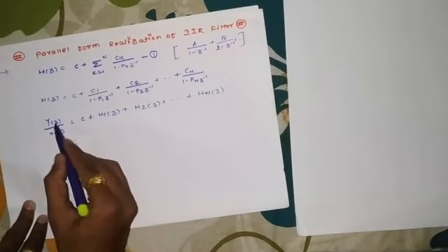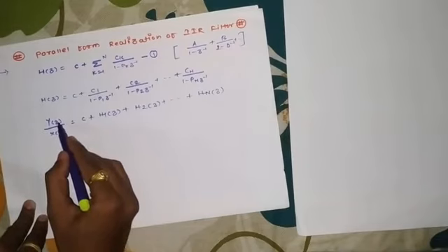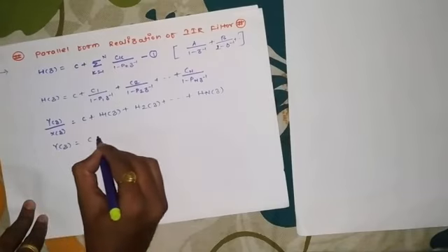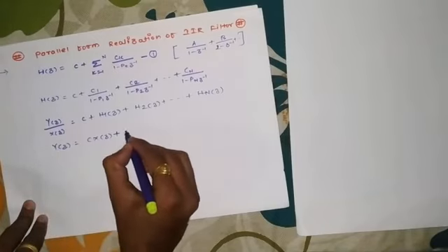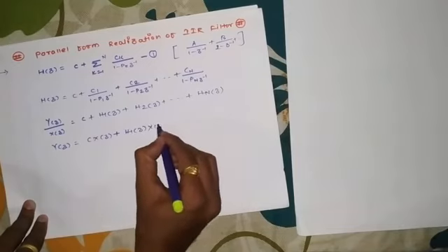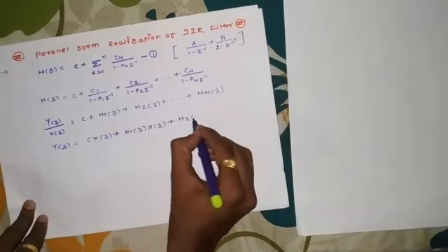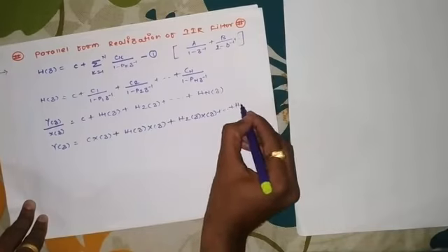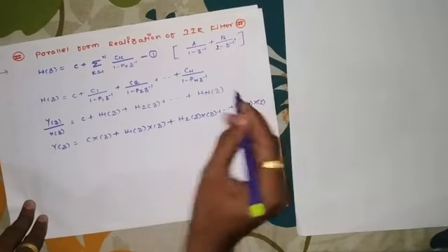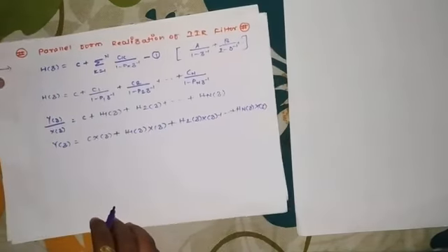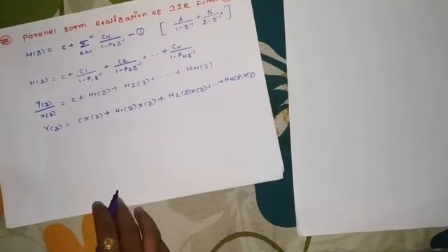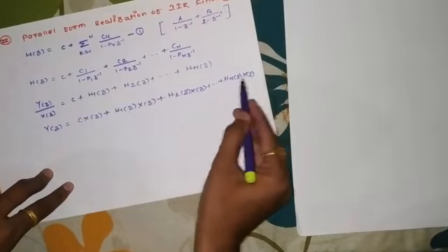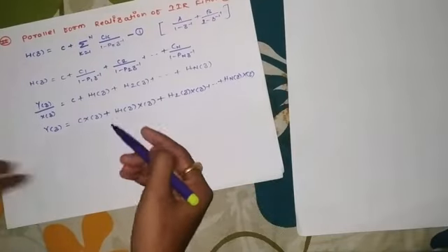Now this equation simply indicates there are certain terms as output Y(z) and X(z). If I multiply, we'll get the same equation as C X(z) plus H1(z) into X(z) plus H2(z) into X(z) plus so on. This is my HN(z) into X(z). Now we'll realize this equation using direct form 2 realization. You can see there are several systems H1(z), H2(z), HN(z). They are connected with each other, that is nothing but they are being added with each other.